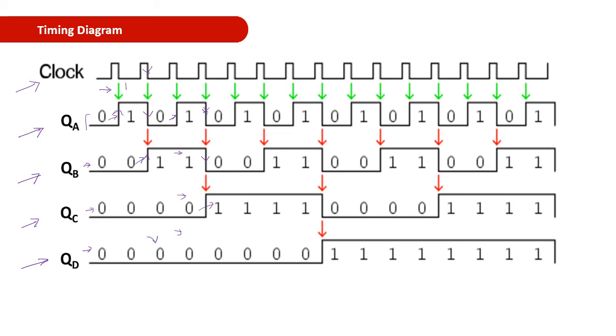So from this I can see that when you apply the clock pulse directly to the A flip-flop, since the JK terminals are connected to 1 1, whenever the negative clock pulse comes at the terminal of flip-flop A, it will get toggled. So it will get toggled for each clock pulse that we apply.